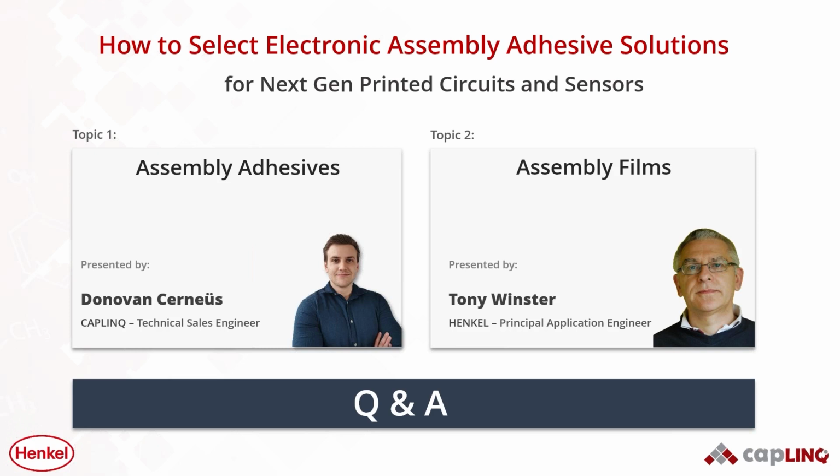Any other questions still pending? Could you comment on the repairability of ECAs versus solder materials? Okay, that is a good question. So I think the reworkability of the ECAs is more difficult because it's a thermoset material. For solder materials, you're looking at a melting temperature where it actually goes to liquid and then to solid, so it's easily reworkable. But for the ECA materials, you would have to remove the entire bond because it's a thermoset material. The material just turns hard and it doesn't turn to liquid anymore.